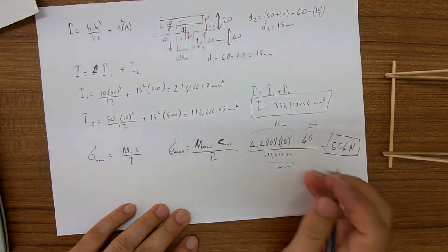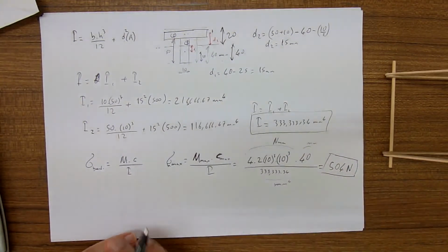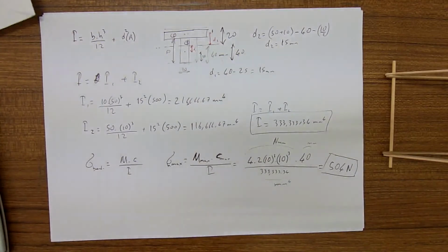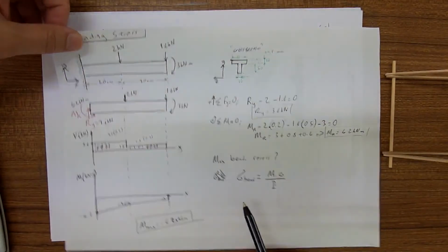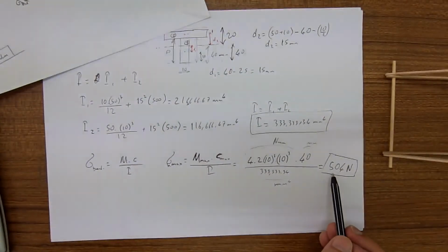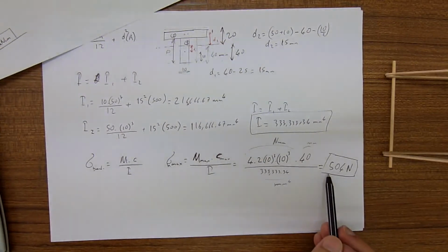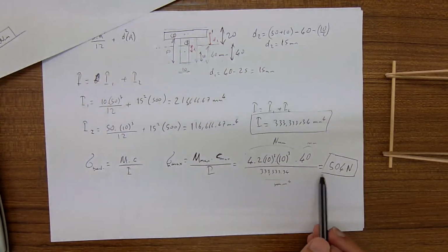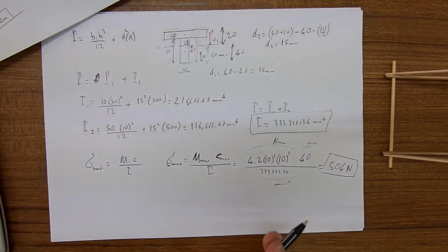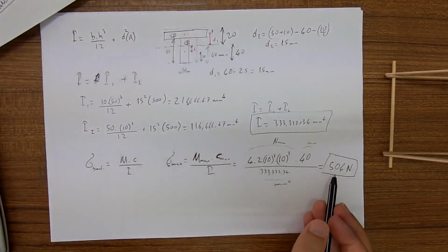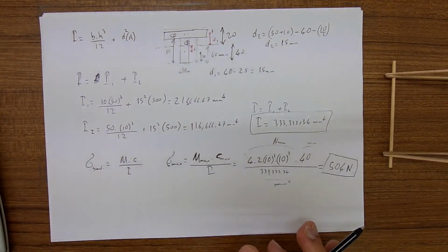So this is the maximum normal stress that can occur under this loading condition. By looking at this value, we can make sure if the structure is safe or not. If this exceeds yield stress, then the structure is not safe under such kind of loading.